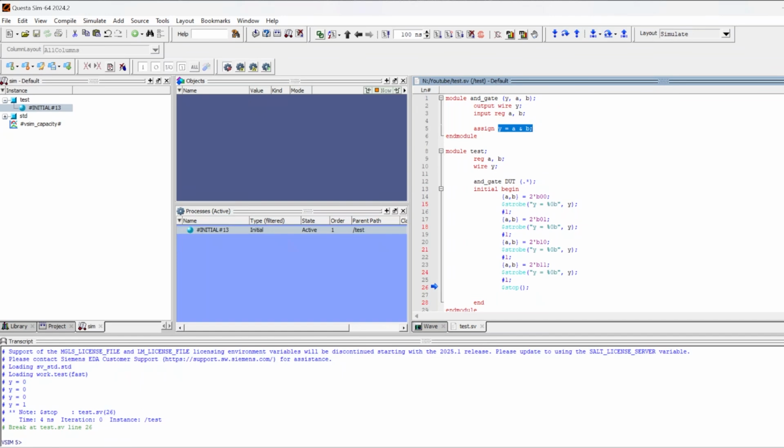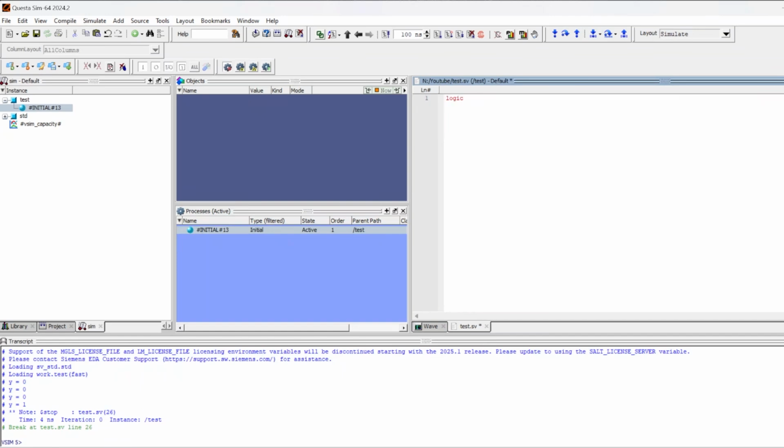And why I said most, you will find out just in a moment. Like reg, it can store values and work as a general purpose variable for modeling hardware. And also it has a plus side that it can be used for both the continuous assignment and the procedural block. So for that particular reason, it reduces the ambiguity and it is more preferred in SystemVerilog RTL designs.